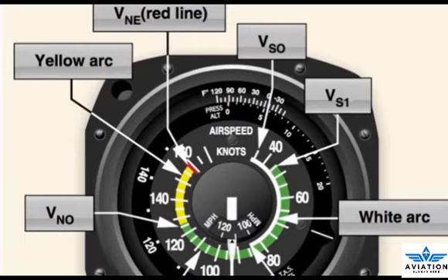Some important airspeed limitations are not marked on the face of the ASI, but are found on placards and in the AFM-POH. These airspeeds include 1. Design maneuvering speed, VA, the maximum speed at which the structural design's limit load can be imposed, either by gusts or full deflection of the control surface without causing structural damage.